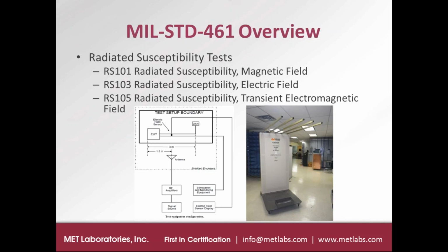One of the things I like to mention to look out for is that prior to version G of MIL Standard 461, at the beginning of the standard, the committee included the entire possible frequency range as part of the name of each test method, even though for each project you don't necessarily end up testing that entire frequency range. I like to point out to watch out for that, because just because a contract might list the name of RS103 as radiated susceptibility electric field 2 megahertz to 40 gigahertz doesn't necessarily mean you need to test up to 40 gigahertz. You have to consider the applicability of that range and ask that question.